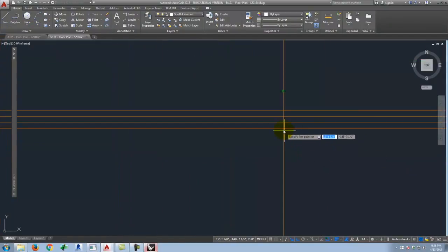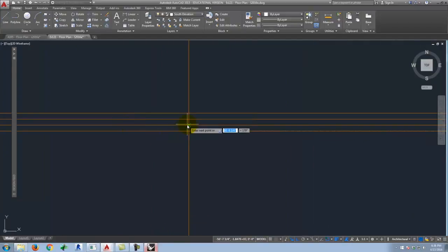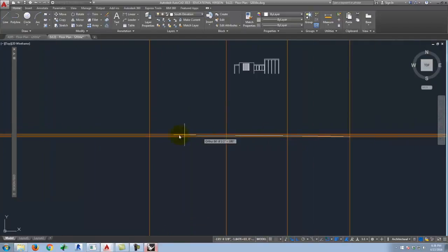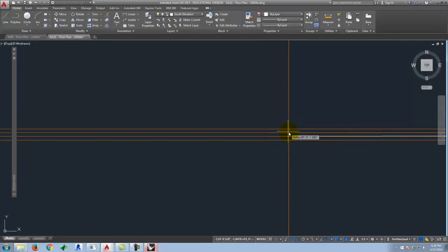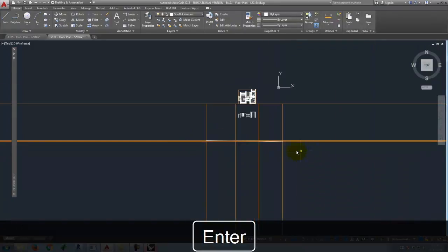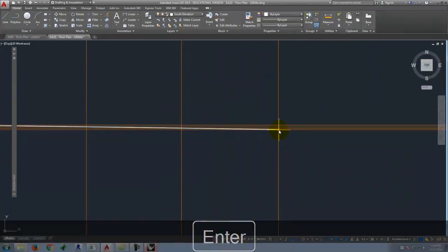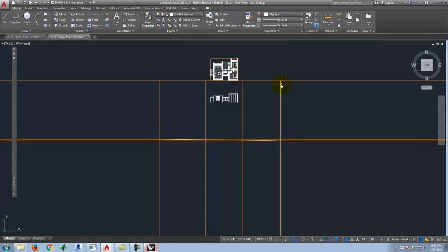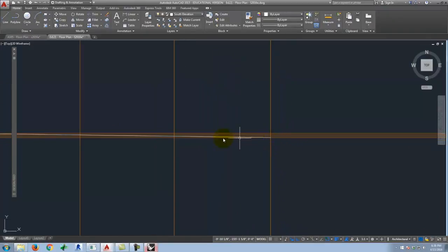And I'm going to go at the lowest point right here to start. I'll go up 1 level to that point. I'll go up 1 level to this point. And I'll go up 1 level to that point. And I'm starting at the low point here because this is the lowest contour that I crossed. So I go up that direction.